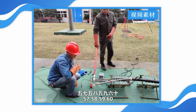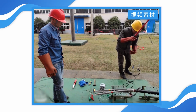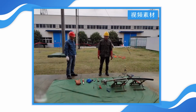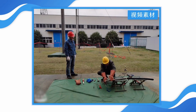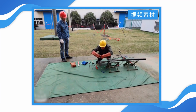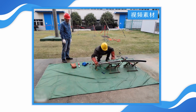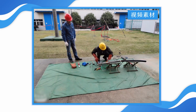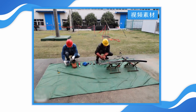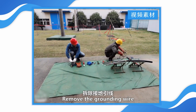Perform discharge. 57, 58, 59, 60. Remove the test leads. Remove the grounding wire.